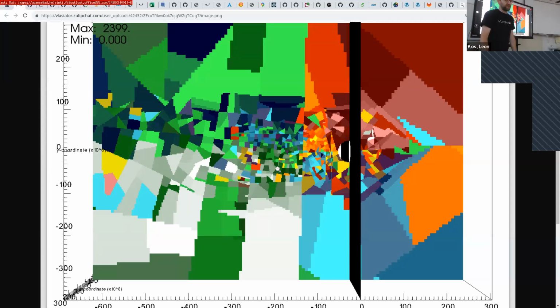And in some cases, if you have a simulation where you have a large density contrast moving very quickly, for example, we have simulations where we have a solar wind shockwave coming in, and then suddenly we get a high density pulse coming in there, then we need to do this more often. But in simulations, especially once you just simulate the magnetosphere with steady solar wind, it has some initial transients, and then it looks very much the same for a very long time. In the late stages of the simulation, we often go to every 100th step or even more.